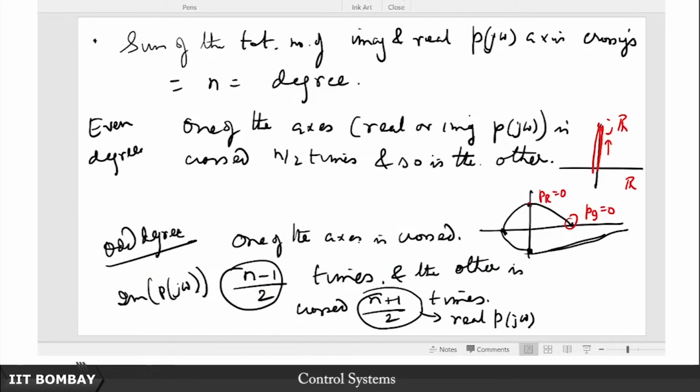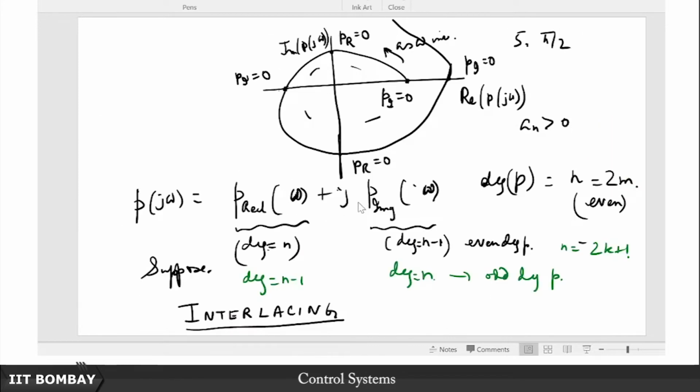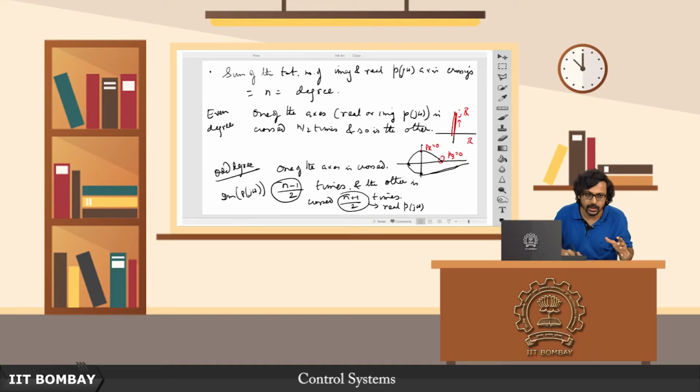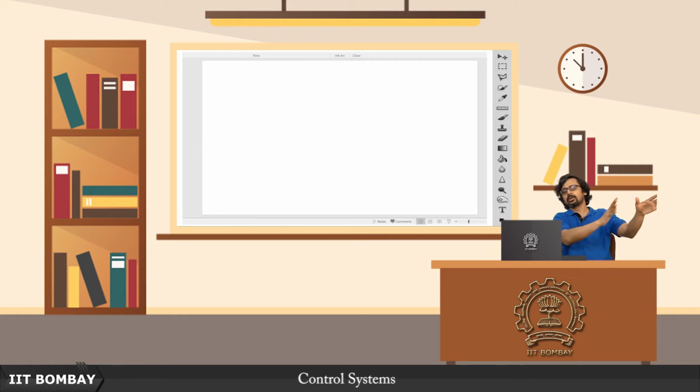So the roots of the even part and the odd part, or the real part and the imaginary part, will alternate as I go along this. Remember, I started with the condition that if all my roots are on the left half plane, then I must have a certain condition. What is that condition? That the phase must be monotonically increasing. These arguments go both ways. The only part I have not proved is that if it is monotonically increasing, then it must have all its roots on the left half plane. I have not proved that, but trust me that these arguments go both ways.